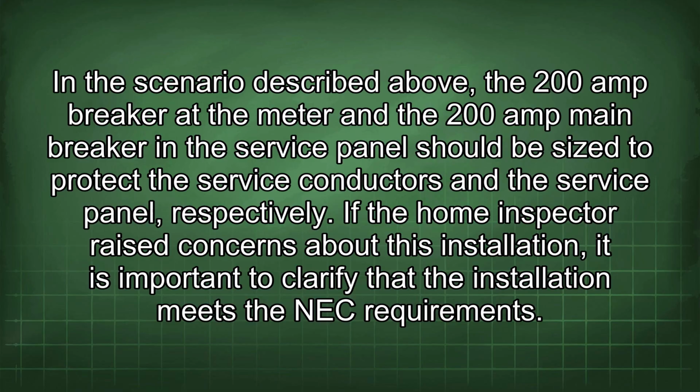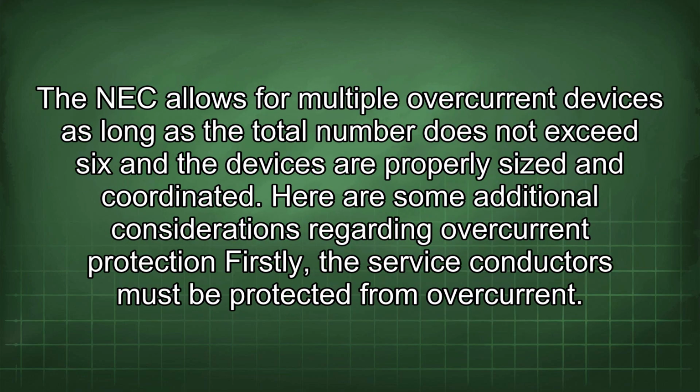If the home inspector raised concerns about this installation, it is important to clarify that the installation meets the NEC requirements. The NEC allows for multiple overcurrent devices as long as the total number does not exceed 6 and the devices are properly sized and coordinated.